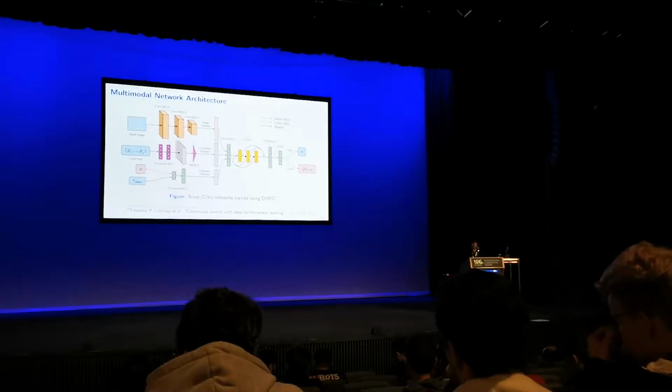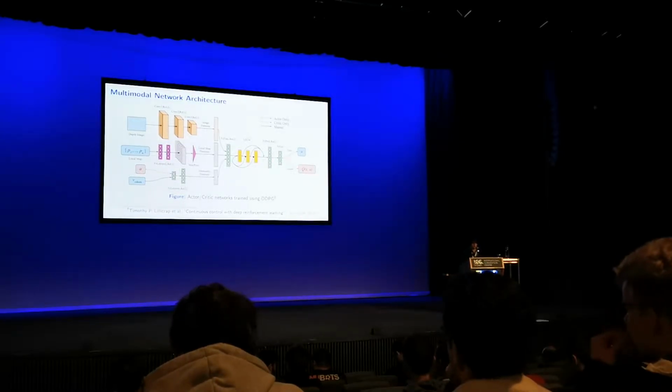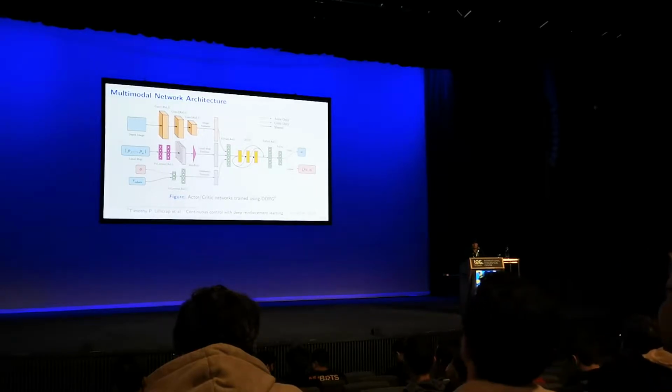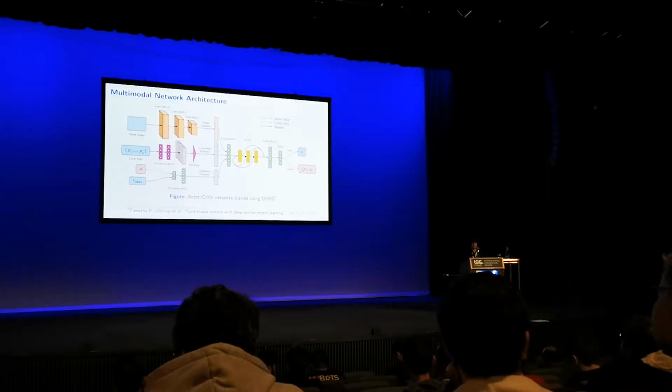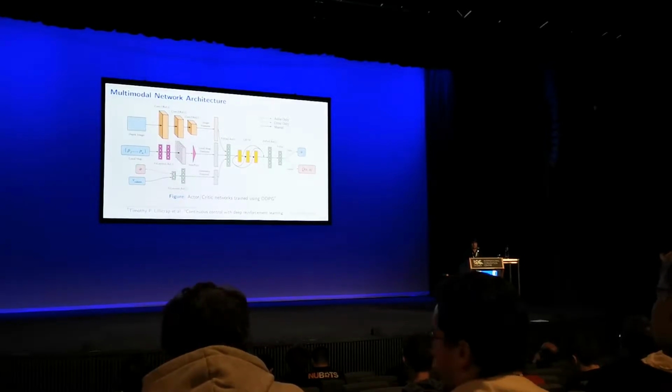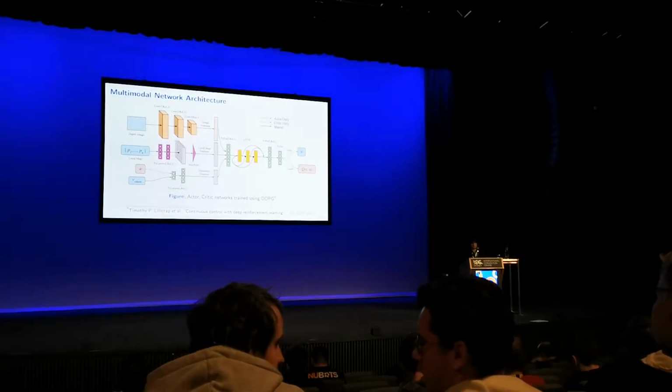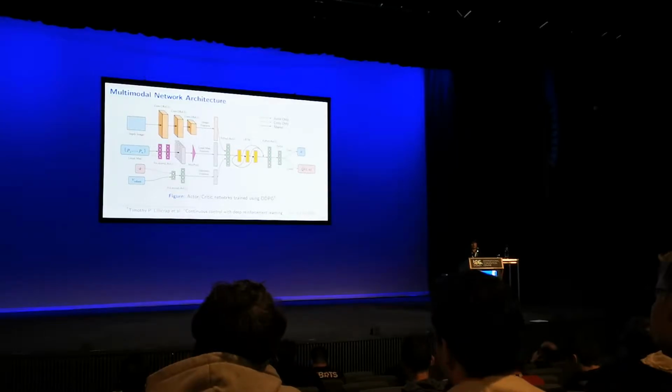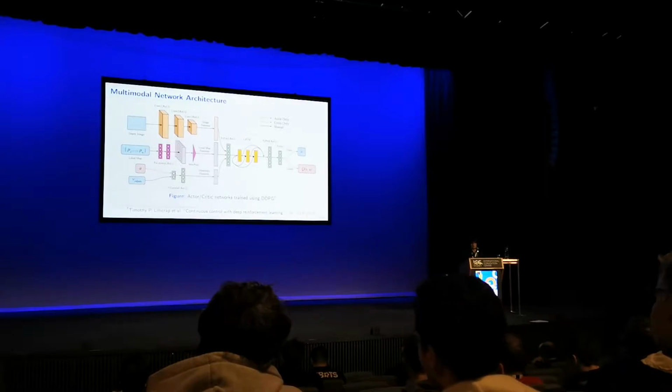So we have an encoder for the image, a PointNet module for the local map, and a simple encoder also for the feedback of the odometry, for the velocities which are estimated using odometry. And we train the system using deep deterministic policy gradients, so the representation here in the slide actually corresponds to two independent neural networks that share the same architecture, but are trained simultaneously.